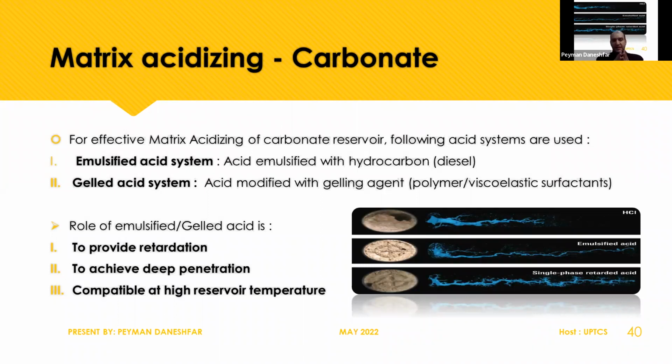The HCl acid, when we use it or when we inject it into a well, the acid wants to go to the first hole that was created before in a well, and again go inside.